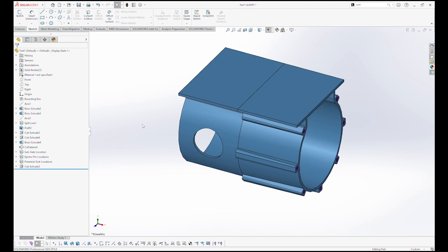Now, I would tell you that that's not for every part. Some of these parts are very tiny. If you have a part that's 20 thousandths in diameter, and maybe an eighth of an inch long, it's oftentimes difficult to get chemical etching or laser etching in a cavity that small. But it's on a case by case basis. I'll also tell you that custom texturing is also an upcharge service, and it will increase the cost of the tooling, and also it will increase the lead time because there's an involved process to make that happen.